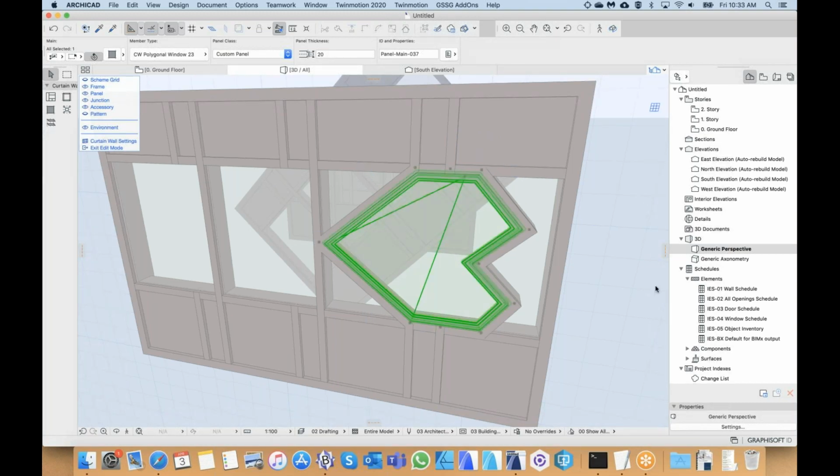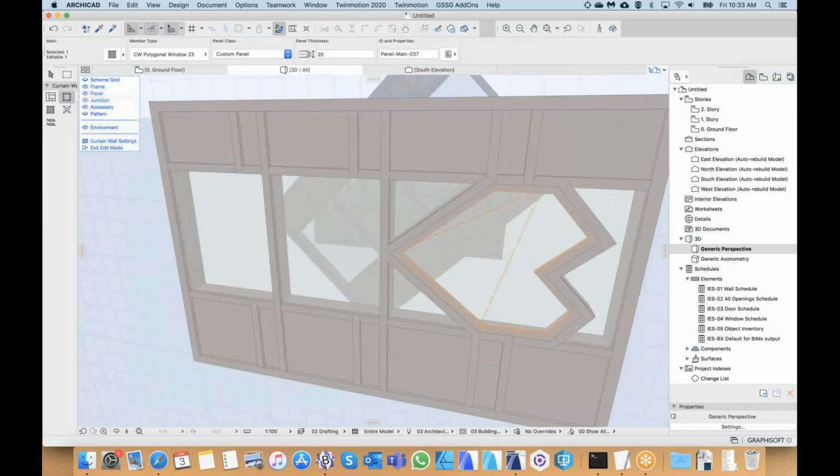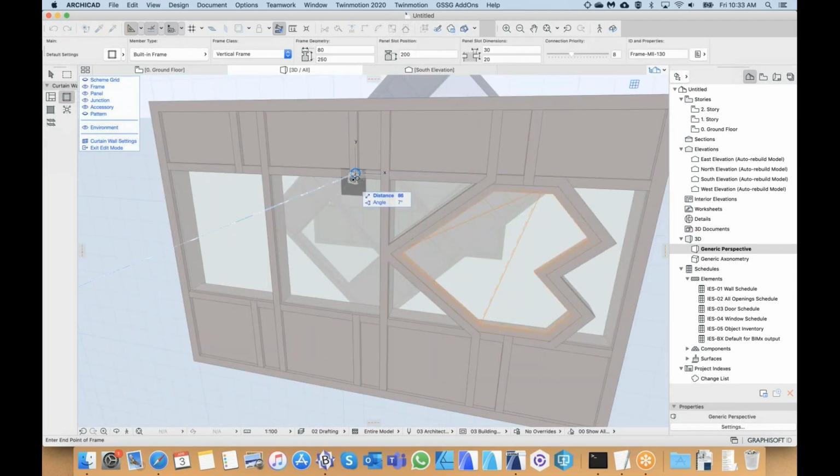Please repeat the insert frame. Okay, that's going back 20 minutes, I think. So to insert frames, we chose the frame tool and we clicked on an open end. When you get the check mark, I'm hovering over to see when my pencil either turns solid or with a line in the middle, and then click. So this is how we can get a frame.